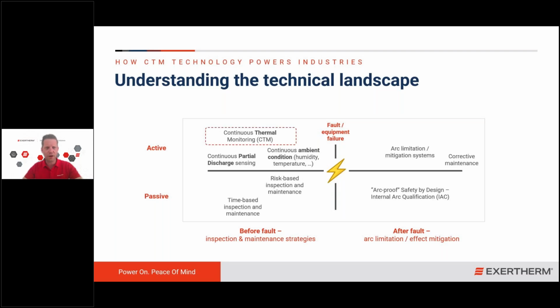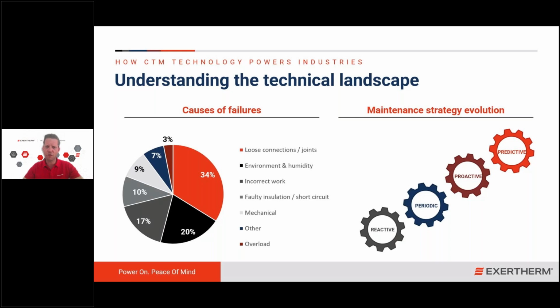And thermal issues are responsible for 1 out of 3 failures in operating power systems. Failures due to loose joints and connections, cables becoming loose over time, or the bolts that are holding busbars together becoming loose over time due to temperature variations, due to vibration or other activities. And then in consequence, the diameter decreasing, the resistance increasing, the temperature increasing, which leads to accelerated aging behavior, and then finally electrical breakthroughs, fires breaking out, and internal arc flashes occurring.